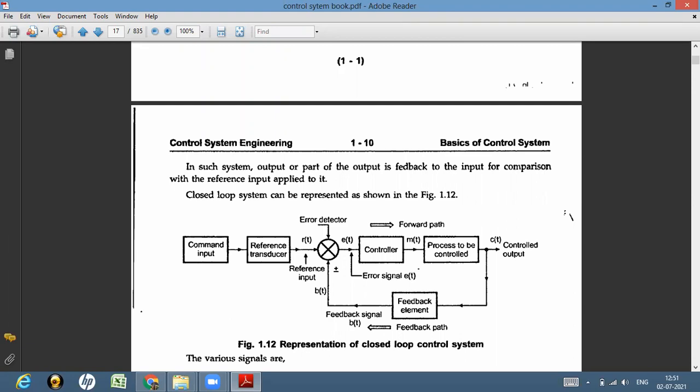सो फॉर गेटिंग दैट डिजायर्ड आउटपुट, जब आपने रिमोट कंट्रोल के साथ अपना टेम्परेचर सेट कर दिया, तो होता क्या है, आपका कंप्रेसर ऑन होगा और वो आपकी इनलेट एयर को कंप्रेस करेगा up till 22 डिग्री or 23 डिग्री सेल्सियस, depending upon whatever the temperature you have set. जैसे ही आपके रूम का टेम्परेचर 22 या 23 जो आपने सेट करा था वहां पहुंचता है, ऑटोमेटिकली योर कंप्रेसर विल गेट टर्न्ड ऑफ. फैन विल रोटेट कंटिन्यूअसली, बट योर कंप्रेसर विल टर्न ऑफ.